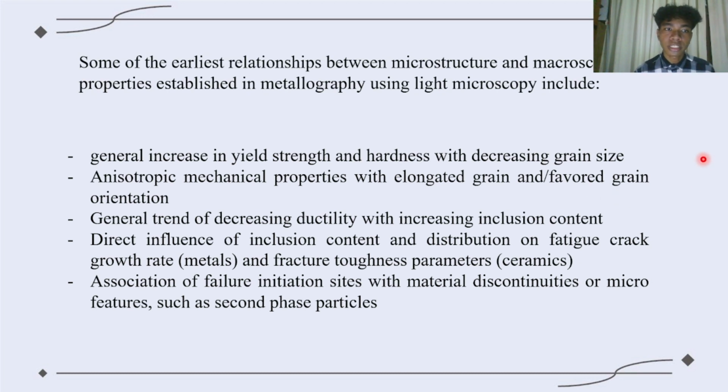the general trend of decreasing ductility with increasing inclusion content, direct influence of inclusion content and distribution on fatigue crack growth rate of metals, and fracture toughness parameters of ceramics, and the association of failure initiation sites with material discontinuity or micro feature such as second phase particles.